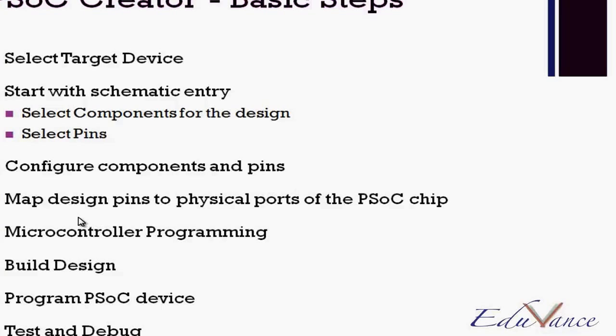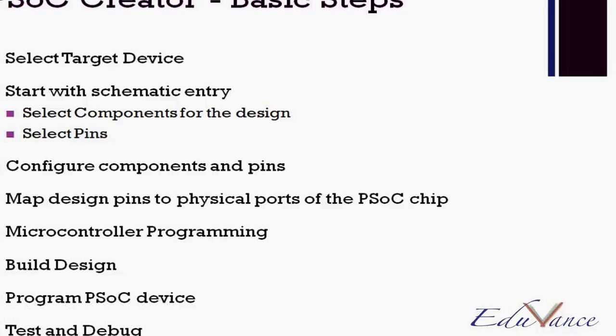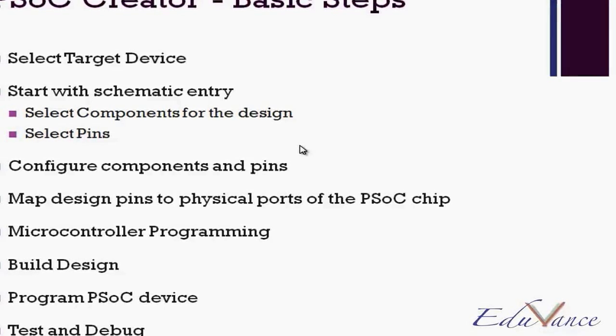Then we will map the design pins to the physical pins of the PSoC chip. We would do the microcontroller programming, we would build the design, then we would program the PSoC device, and depending on the output we would test and debug the design. Okay, again I'll revisit these points as we are doing the experiment. So let's go ahead and look at the PSoC Creator software.